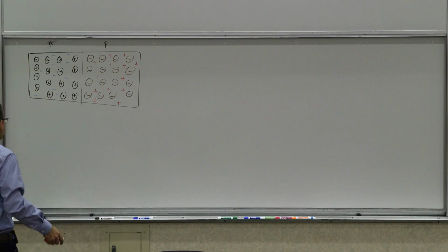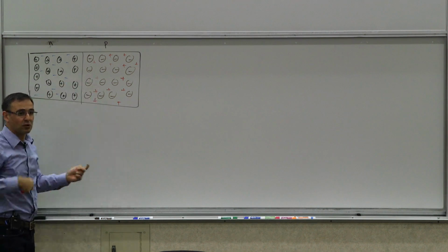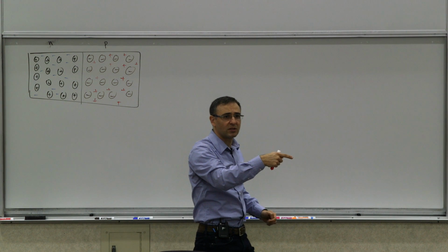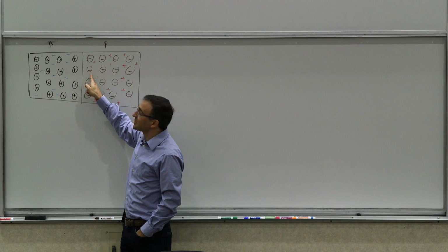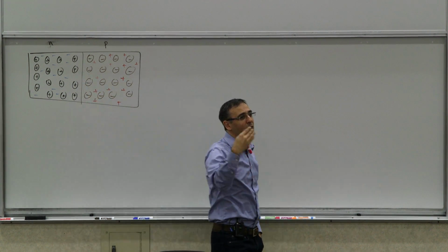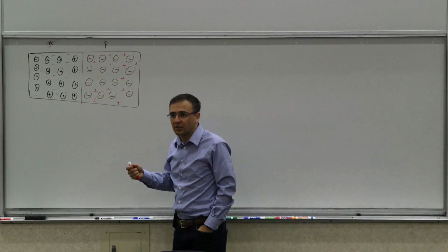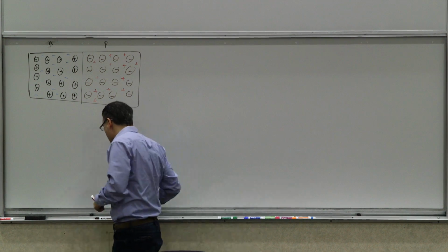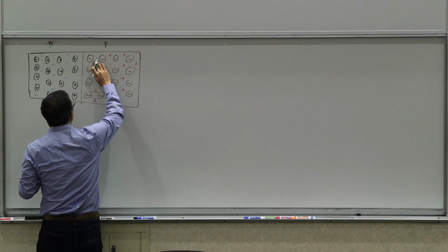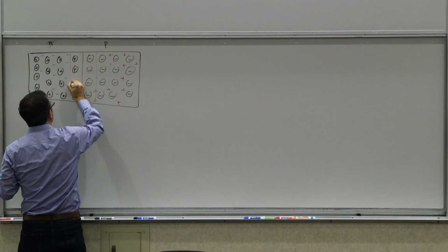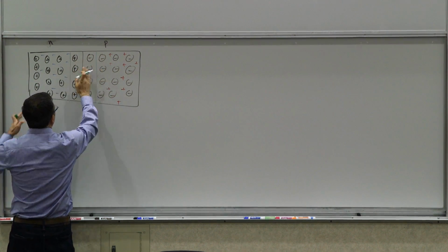And these being small devices, it's very quick, the chance of these guys ending up on the other side is pretty high, because they're moving around, and every so often they will end up on the other side. For example, an electron moving from this side and ending up on the other side is a minority carrier, because now there's a lot of holes around it, and it has a high chance of recombination. Now, the closer you are to the junction, the higher this chance is, and it's really an exponential drop beyond a certain point. But at that point, there is a region. You basically eventually form a region which is depleted of charge carriers. So most of the charge carriers in this region have already recombined.